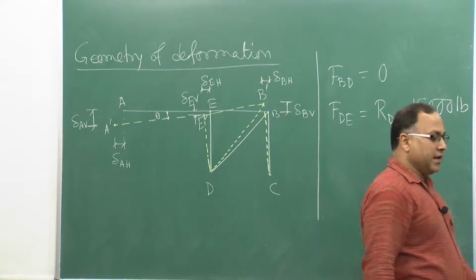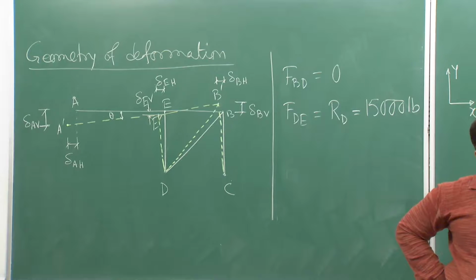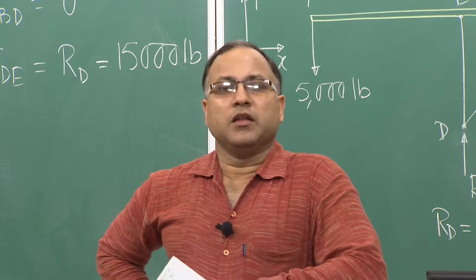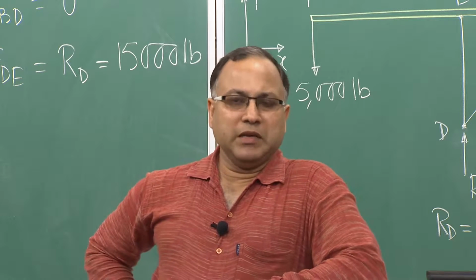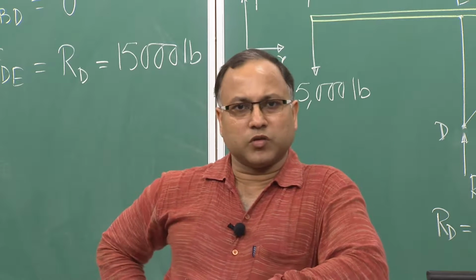If it is not carrying any force, what can you conclude? There is no deformation in that member. Deformation will happen only if the member is carrying some force.